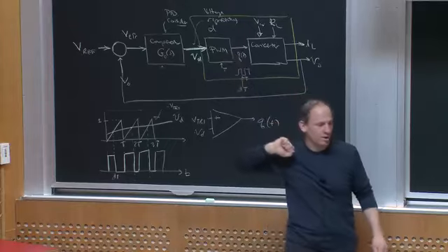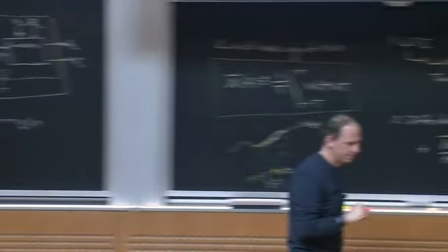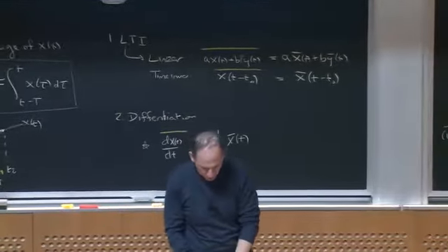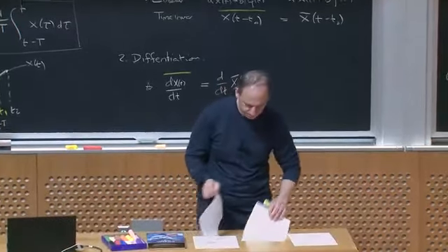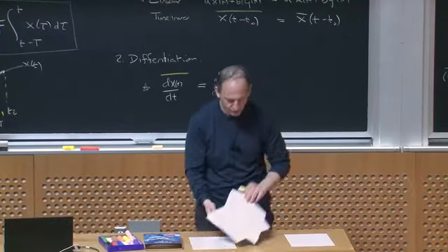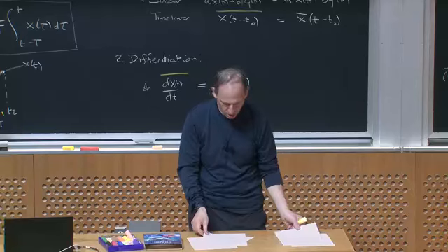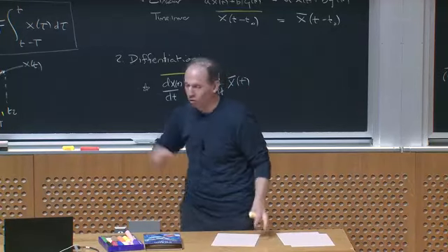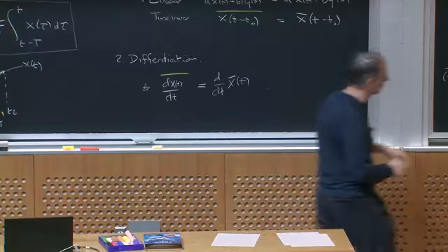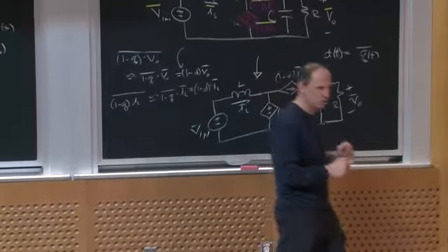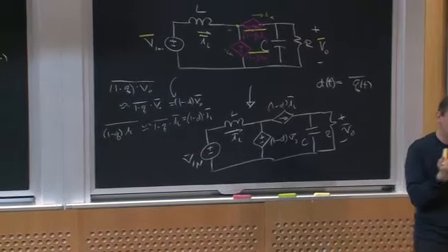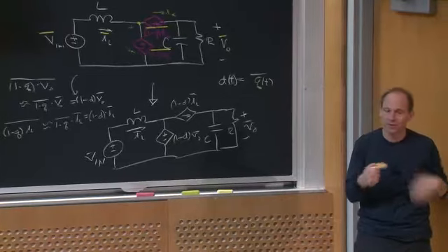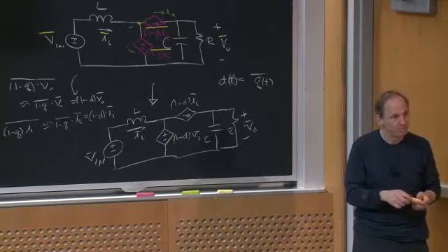Now we're going to take this up next class, okay? But I wanted to show you the basis for doing this. This is really useful for building control models for converters, because now I've gotten rid of all the complicated switching stuff but it still gives me the low frequency dynamics that I want to deal with in my controller.